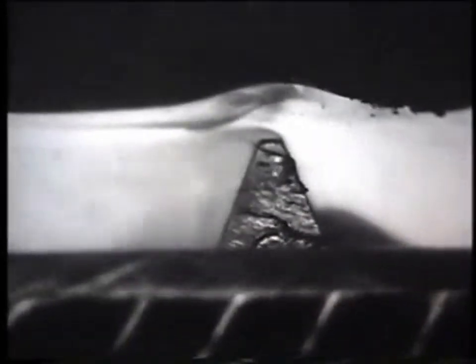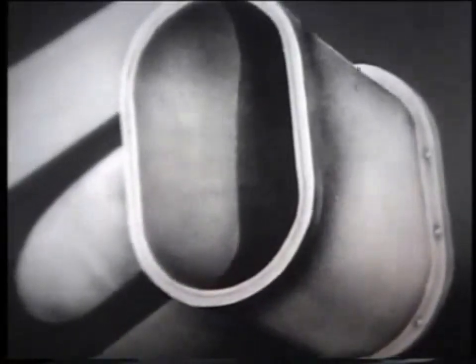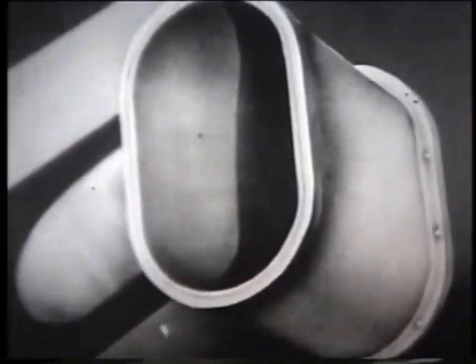Usually the gap between the electrodes is 0.05 of a millimeter. The smaller the gap, the higher the processing performance and accuracy. This property is used to localize the treatment by choosing the appropriate shape and size of the electrodes. The process can also be localized by applying an electrical insulating layer to non-working areas of the tool or part.